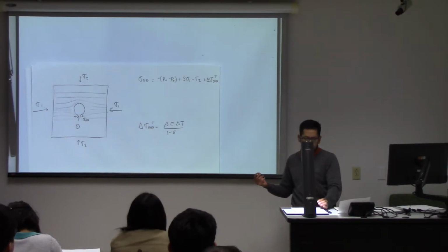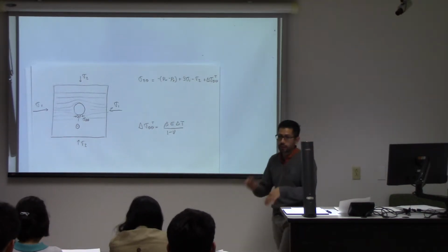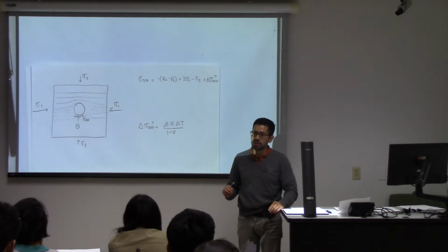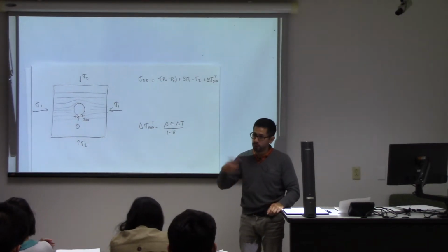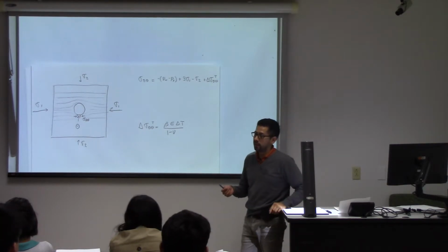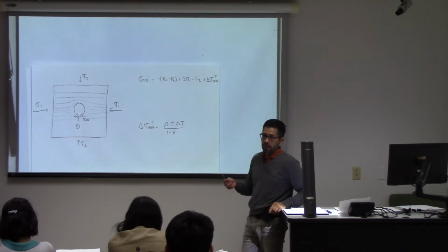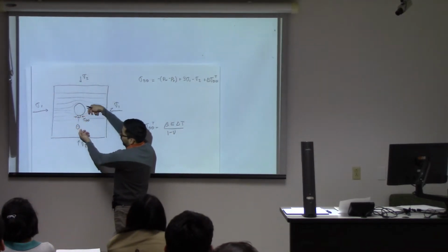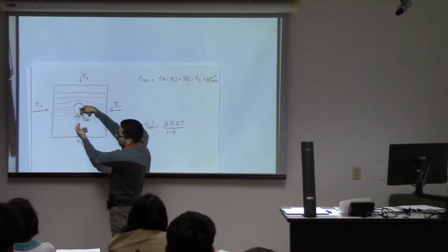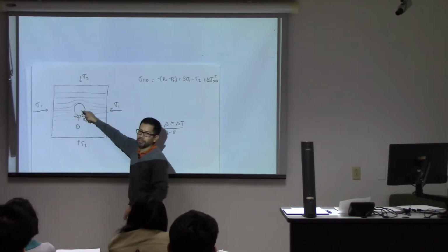In something that we're going to see later on, actually I'm writing right now the chapter on wellbore stability, something that you're going to need later on, but you're going to have to go mostly on your own through that. We're going to see that when we have lots of compression in one direction and not much compression in the other direction, here we're going to have shear failure.